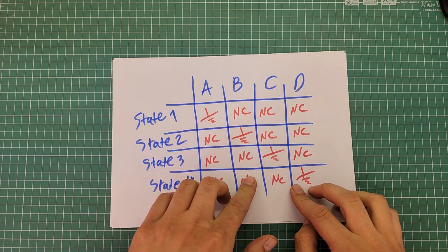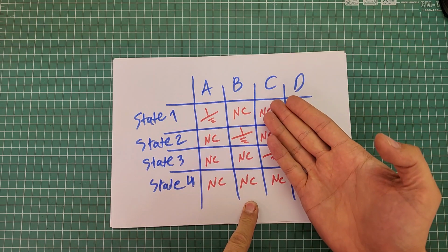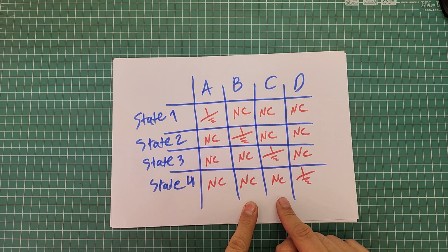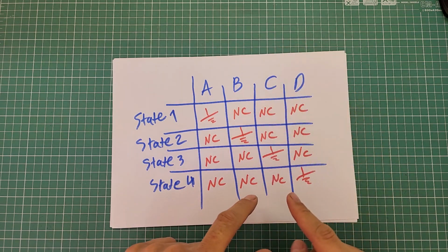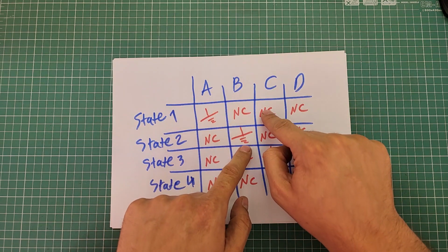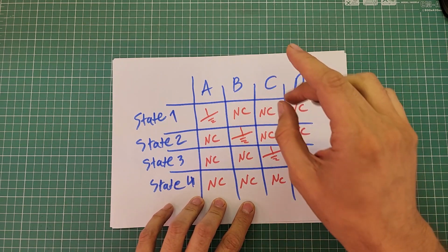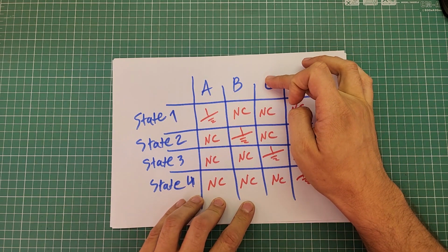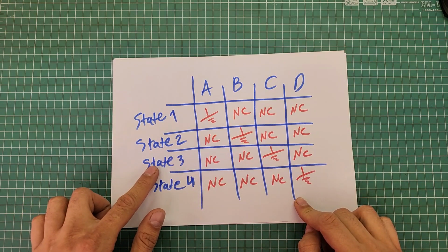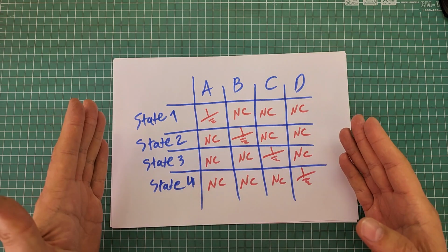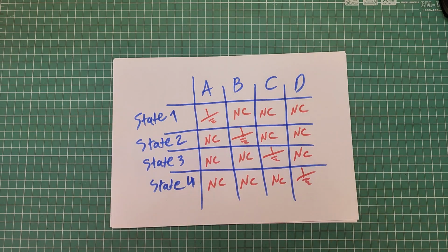You have to decrease the PWM on winding B from 100% to 0% gradually, and at the same time you have to increase the PWM on winding C from 0 to 100%, like this. When the PWM on winding C reaches 100%, it means that this step is completed and you have to take the next step. Next step is to go from state 3 to state 4. You can repeat this process to take more and more steps. I'm going to write the PWM based driving program and test the new driver.